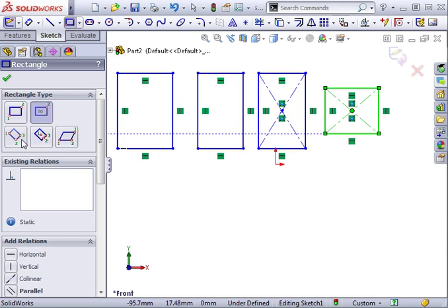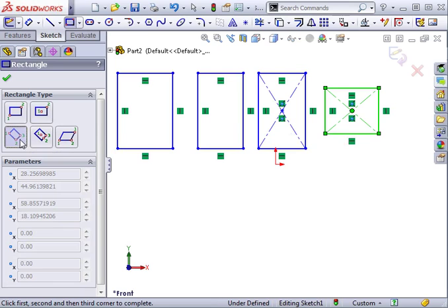Circles and arcs are defined a bit differently than lines and rectangles. Let's start with a circle. If I open the drop-down menu for the circle tool, you can see that I have the option to create a regular circle or a perimeter circle. I can also access the circle tools from the S key shortcut menu or with mouse gestures.